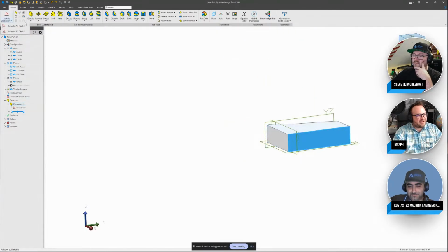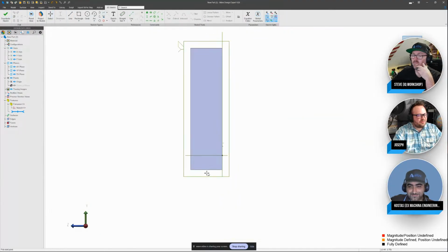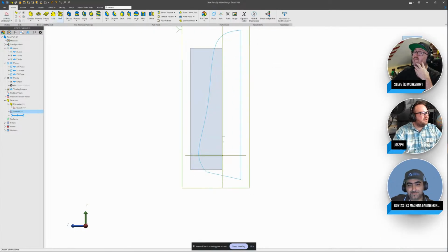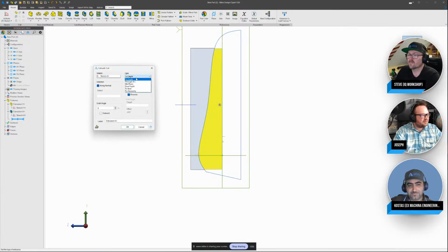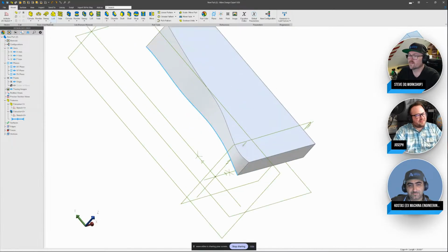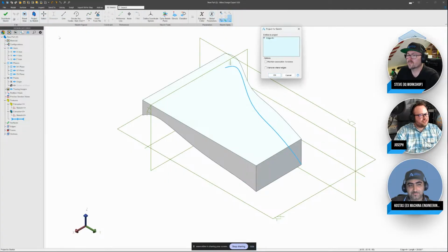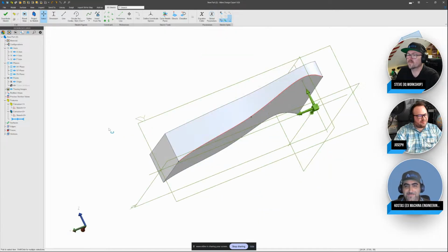But here, I make a kind of difficult path in 3D space, and then we'll not extrude, rather cut through all. There we go. Now I can take this edge, go to a 3D sketch, and make a projected 3D sketch of that edge so that we have that crazy path.